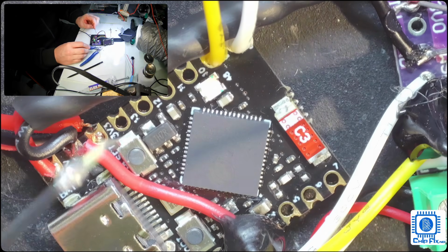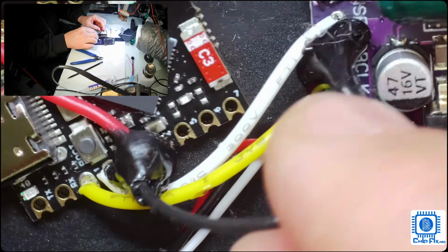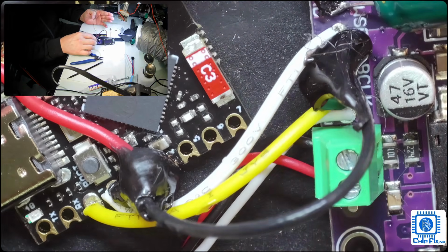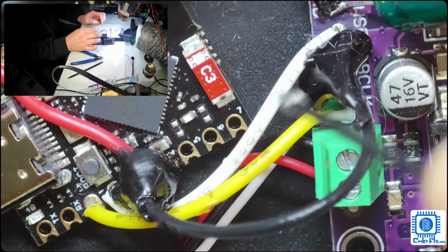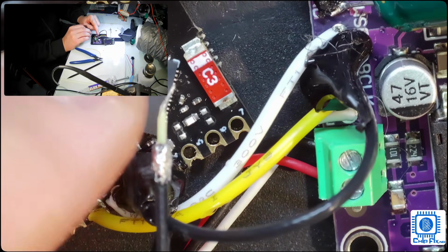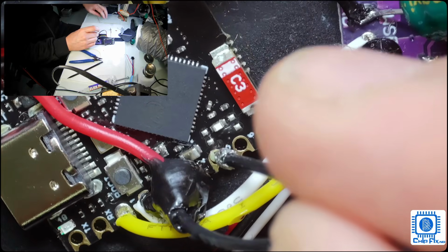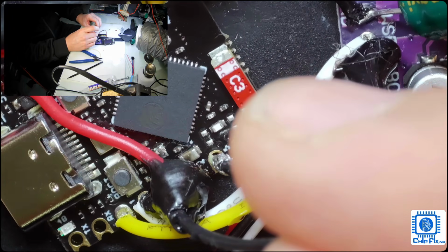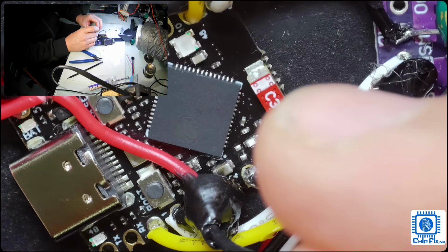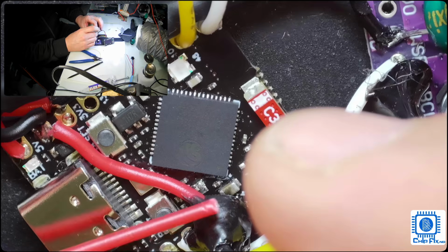So I use it for the data cable here, the data signal for I2S, and I put it in. So this core goes into the GPIO, and then I have attached a cable to this braid, and it's going to ground over here. I will show you here. So it's going from ground to this shielding.